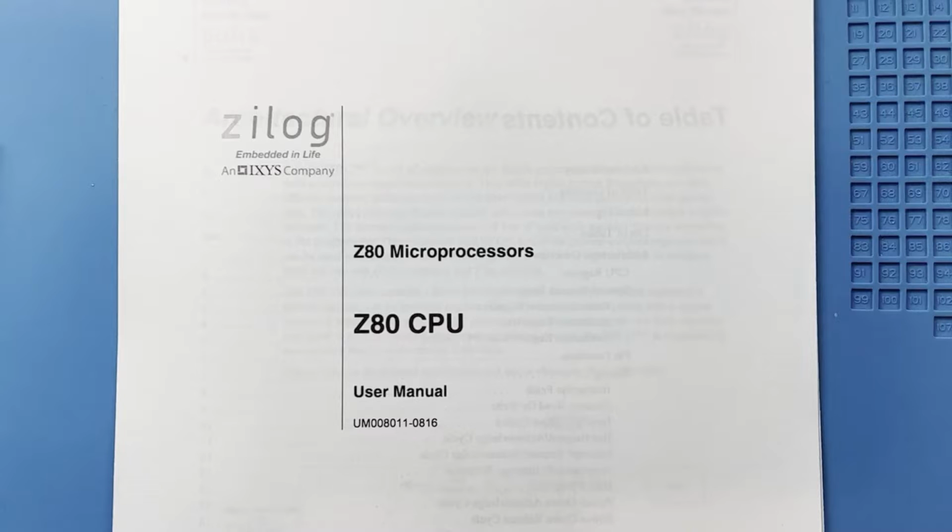Because of its ease of use and popularity, it's still being produced today, although they've increased the speed of the processor. It'll now run from 6 MHz up to 20 MHz. Having it ready, available, and at a low cost is a great benefit for this project. Another benefit of using this processor for our project is it has no lower boundary on the speed. We can set up a button for the clock and manually step through the instructions, which is great for debugging.